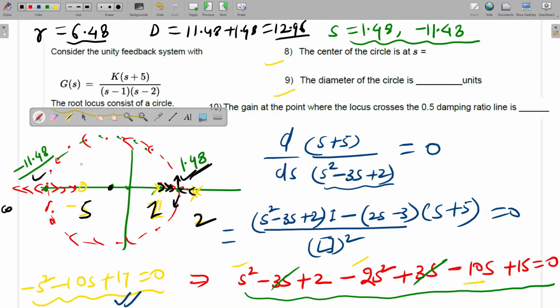That is a positive value. Again, these poles are moving here, entering into the real axis. Okay. So this will be the break-in point. After that, one pole will go to this 0, and one will tend toward infinity, because 1 zero will be at infinity. Is it clear? Yes, sir.